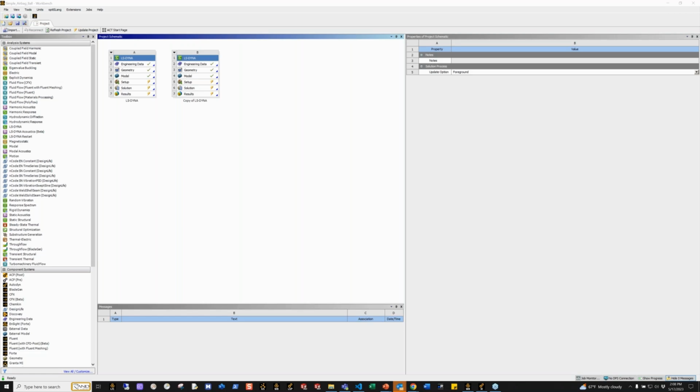But that's really all you have to do, is to make sure you have a very small amount of gap, such that only the first few cycles within your explicit analysis are going to have no contact, and the rest of it is going to just impact. So to answer your question, in simple terms, let's just make sure you do your geometry prep correctly. I think that's gonna mostly do it. Hopefully that answers your question.